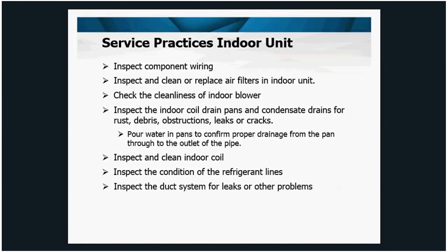You should also check the duct system. Now, leaks in duct systems rob capacity. If you've got an air leak in a duct in an attic, it's going to either pull in hot attic air or it's going to eject conditioned air into the attic space and not do the homeowner any good. The other thing you want to look at is crushed ductwork, disconnected ductwork, things like that. So always inspect your ductwork, make sure it's in pretty good shape.